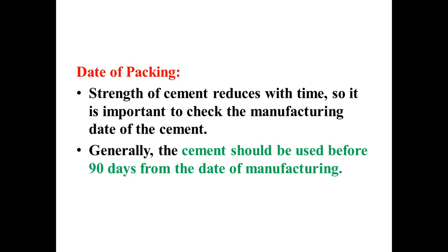If lumps are generated inside the bag of cement, then we cannot use it in the construction. So the maximum number of days from the manufacturing day is 90 days, which we have to strictly follow. Within that period of time we have to consume it. Later on we can procure the cement again and use it.